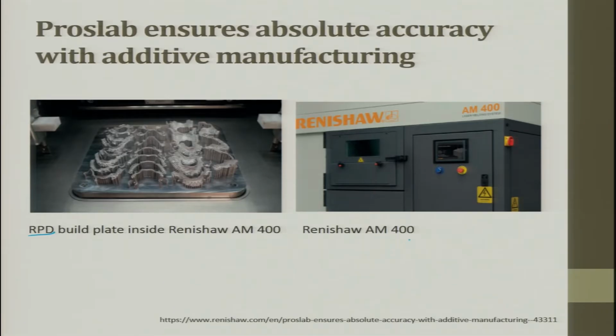Here you can think of using a laser as a source, or you can think of using an E-beam as a source. Moment you go for E-beam, you have precise control. Laser has its own advantages and disadvantages. So, you use any one of the sources inside the machine and start using metal powders. Powder means it is not pure powder, it is an alloyed powder. Mix it and then you can start getting it.